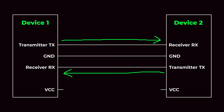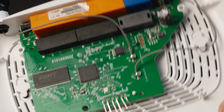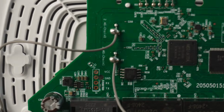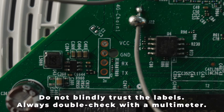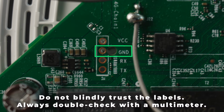Anyway, now we have what a UART connection looks like. And that's exactly what we have to look for. A group of 3 to 4 pads or pin headers on the PCB. And sometimes the vendor makes it real easy by labeling them. And lucky us, that's the case with this router. See, here we have the labels that belong to UART. TX, RX, ground, and VCC.